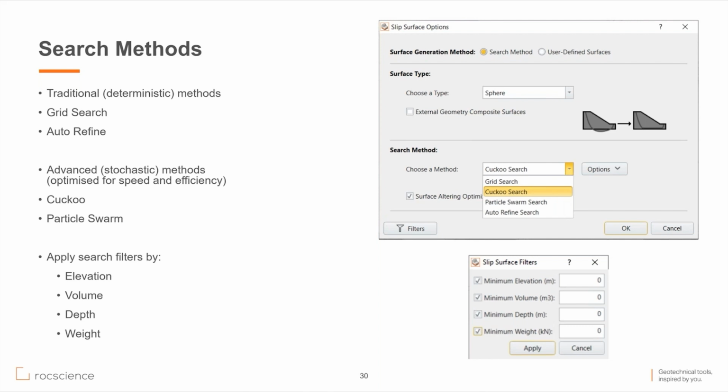Rocscience does have minimum specifications for 3D software. At the bare minimum, if you are using these larger data files, we would recommend going for the recommended computer specs or above, not the minimum, if you are looking to process quite detailed topo files. But certainly most of the Slide3 models, RS3 models I've built have used real survey data to define the external, so it's done quite commonly.